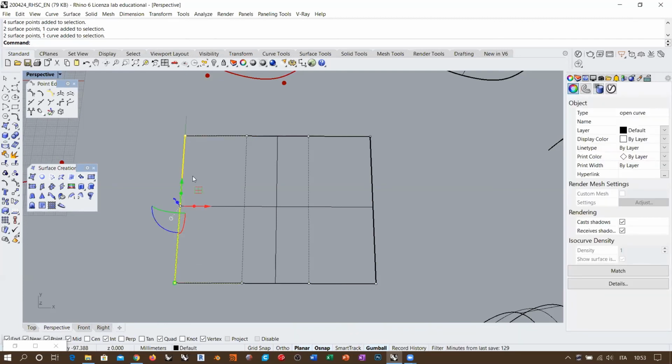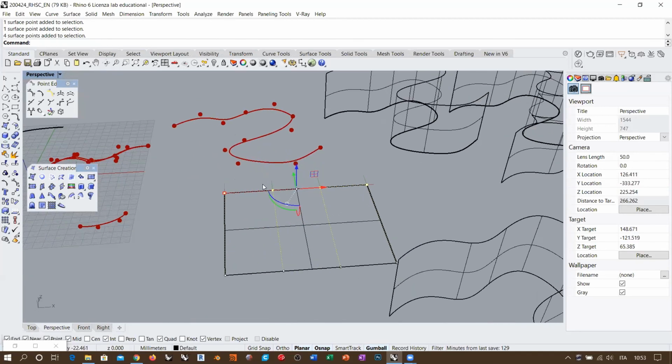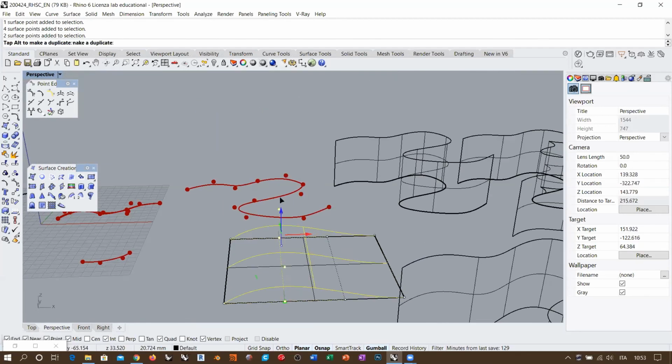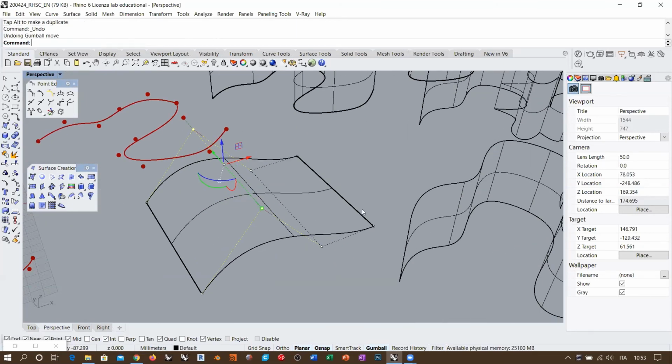So degree 1, one control point here and one control point here. But the flow on the surface through two simple cross sections happens with degree 3. So this surface is already deformable internally in the cross direction with a degree 3 deformation, so organic deformation.